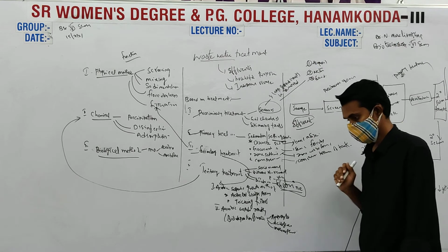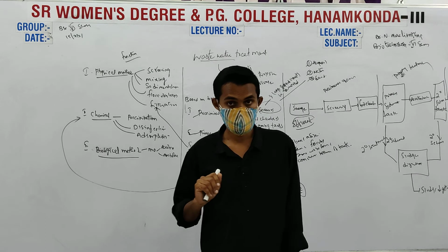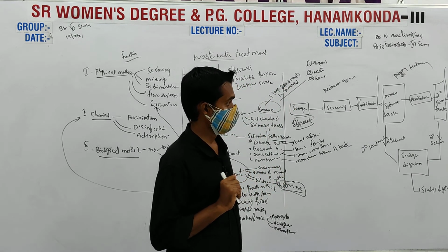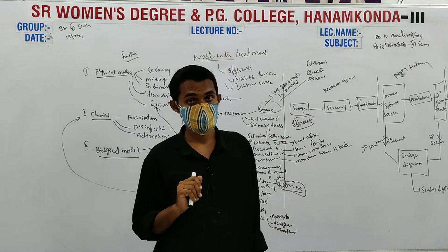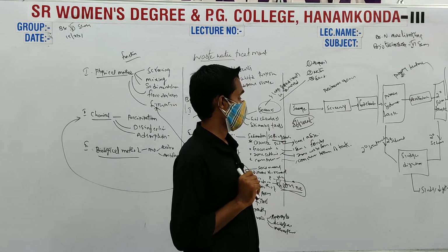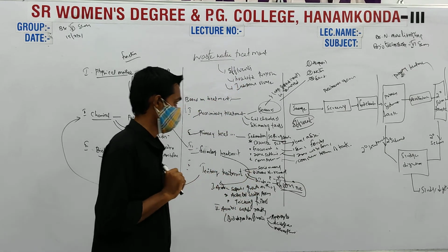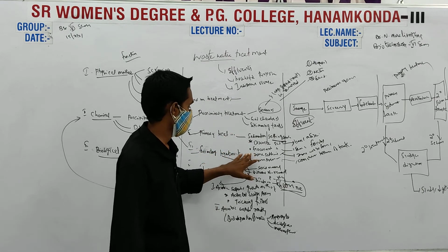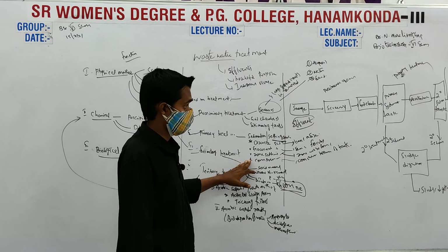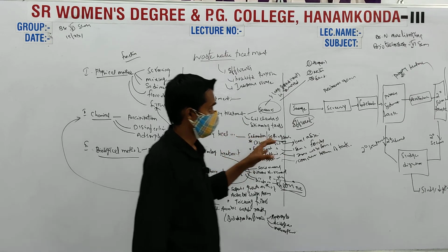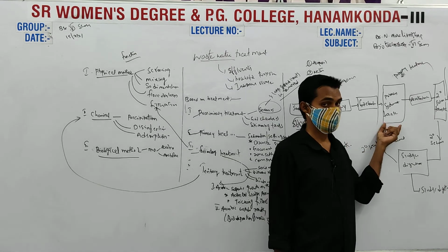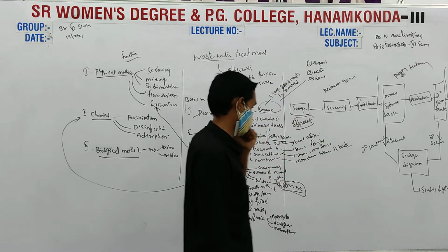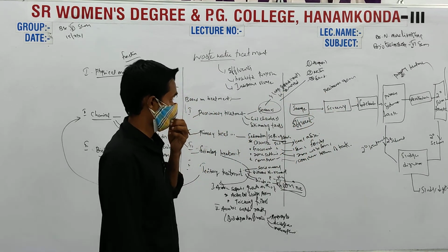Whatever remains of the wastewater has to pass through the sedimentation tanks, one primary sedimentation tank and one secondary sedimentation tank. The particles get sedimented, either by discrete sedimentation, flocculent sedimentation, zone settling or compression. These are the different methods happening in the primary or secondary sedimentation tanks.